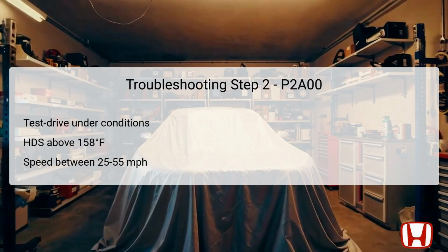The Honda Diagnostic System, HDS, must indicate that the engine coolant temperature, ECT sensor 1, is above 158 degrees Fahrenheit, 70 degrees Celsius. This temperature is significant because it confirms that the engine is at a proper operating temperature for effective performance testing.